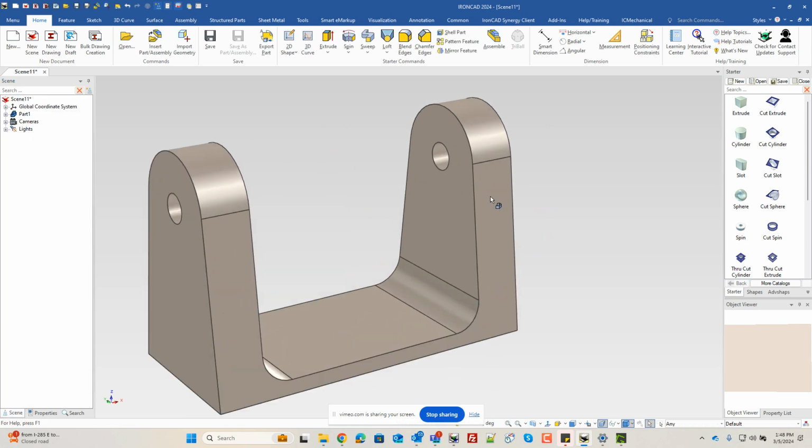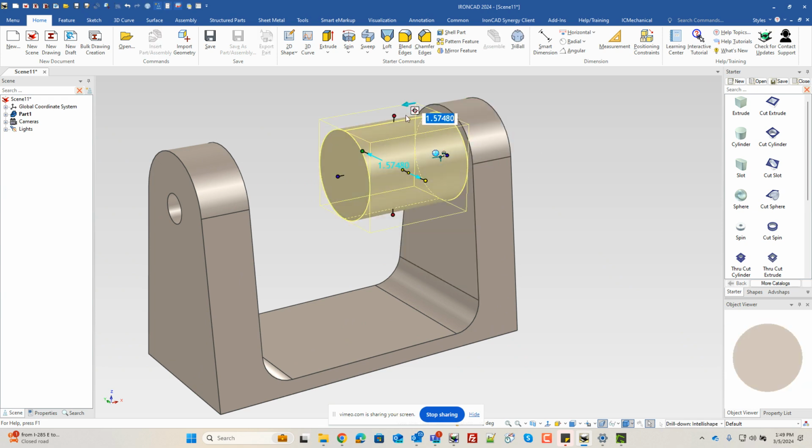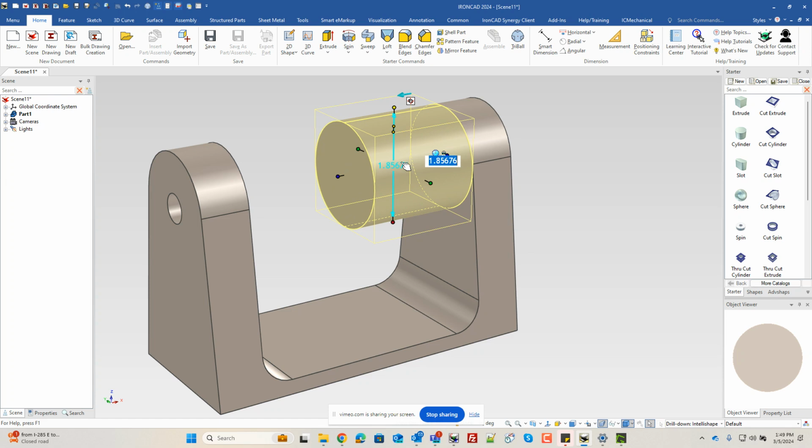And now we want to do the cylinder on here. We're just going to drag and drop a cylinder here, and then we can snap it up here. We didn't know that value before. And again, we also don't know this value here. We have to do some calculations. So we can just double click on this handle. We know it's going to be 4.25 minus 3.5.